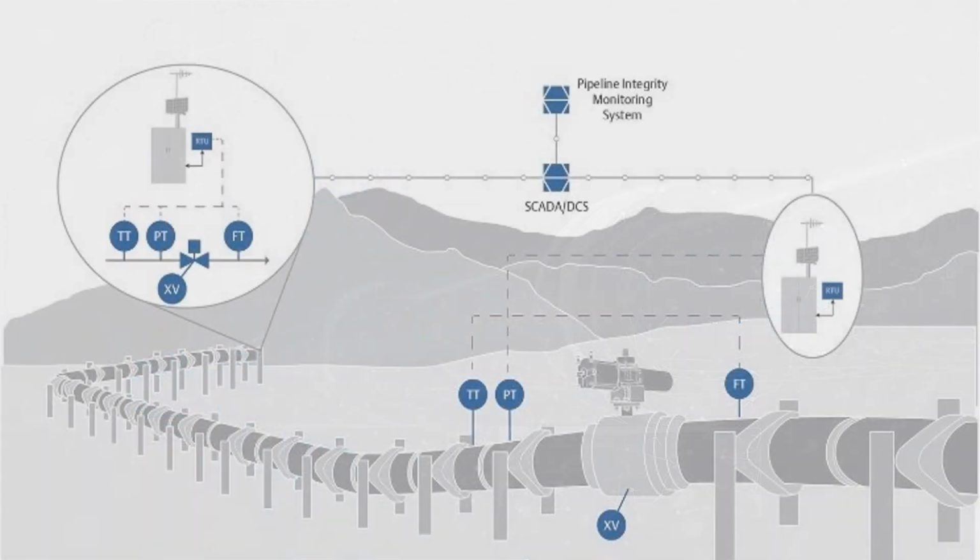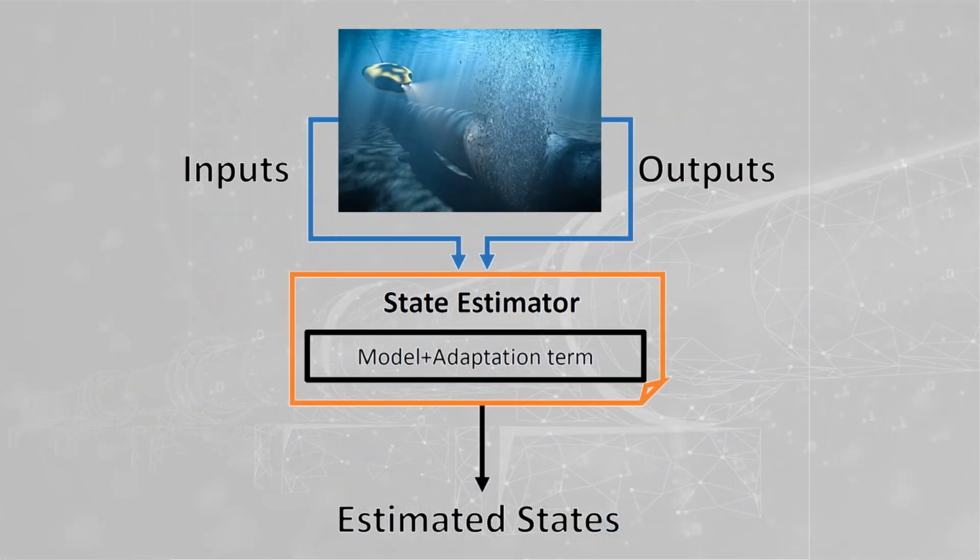This implies that we only have measurements with high precision at the measurement points, nodes, and for the rest of the pipeline it is necessary to estimate what is happening, based on the observed variables. This can be achieved by the physical model that mathematically explains, through differential equations, the flow of the products moving in the pipe. This is a typical case of application of the Kalman filter, KF.